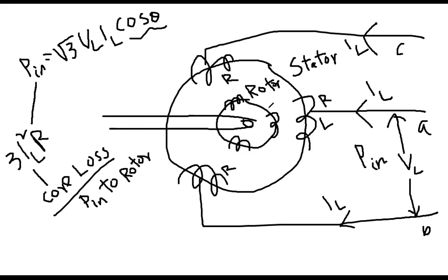We discussed the working principle of induction motor: voltage will develop on the rotor coils, current will flow, and it will produce another set of flux. Because of the interaction of the flux, this shaft will move, but still the shaft is not rotating. So now come back. This is the input power to the rotor.